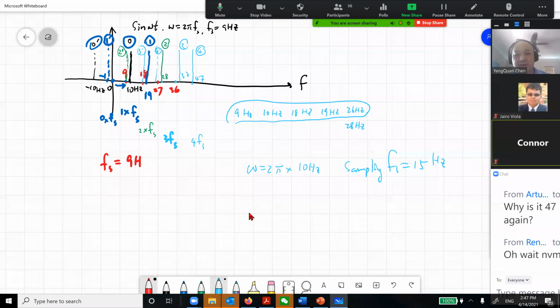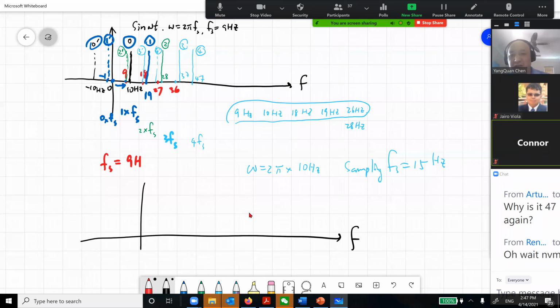Okay. So let me do the same thing here. So I have the frequency in here. So my original is 0 Hertz. So 0 times Fs. Okay. So then this is my 10 Hertz. Okay. Actually, in our system, we use the 100 and I use the 150. Okay. But according to the sampling theorem, you have to sample 200 Hertz or higher. But now I didn't sample that fast. I sampled slow. So we'll see what's going on.